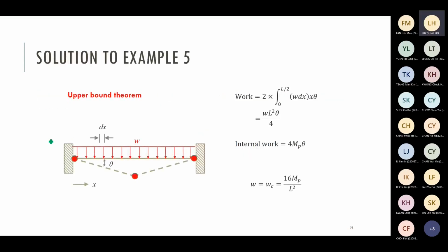This relies on some understanding of mechanics. How to calculate work for a beam under uniformly distributed load, UDL. Fixed end beam. For a fixed end beam, there are 3 plastic hinges formed before collapse. One, two, three. For a fixed end beam, the number of hinges is equal to 3. Two on the two sides, the last one at the middle.